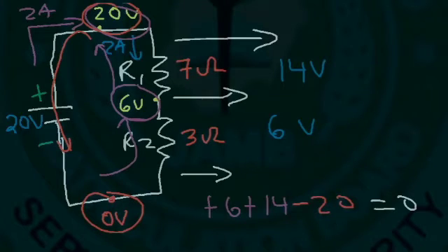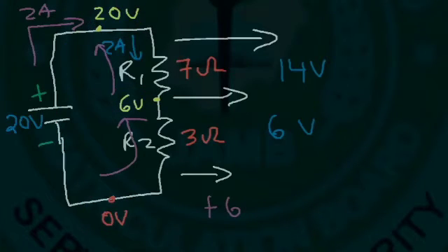If you look at the potentials, the absolute potentials across the circuit, and view it that way, it's going to be a lot easier to write the Kirchhoff voltage expression. Now let's calculate the power delivered by the battery.